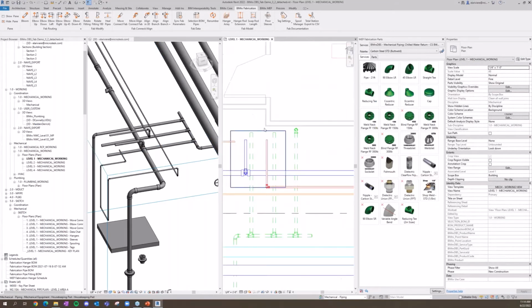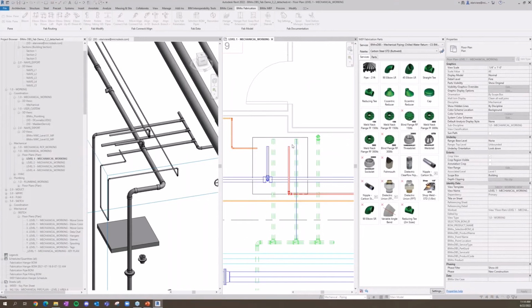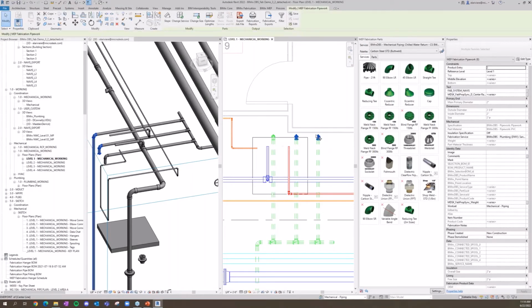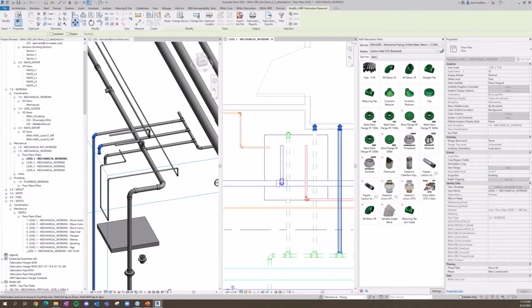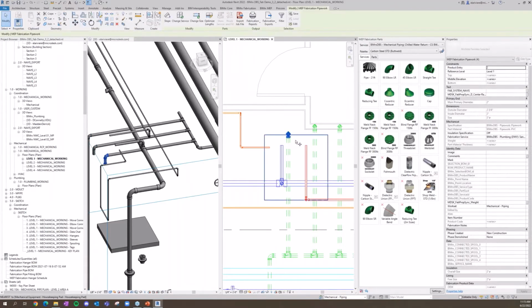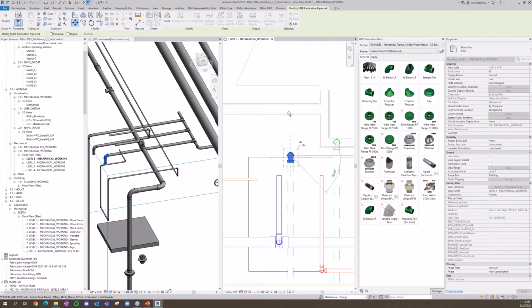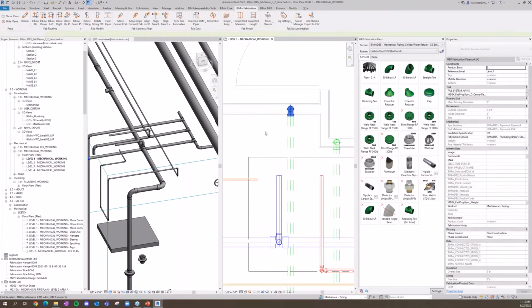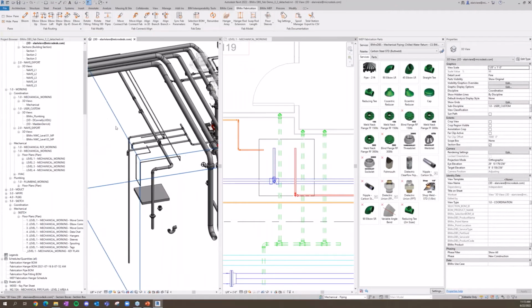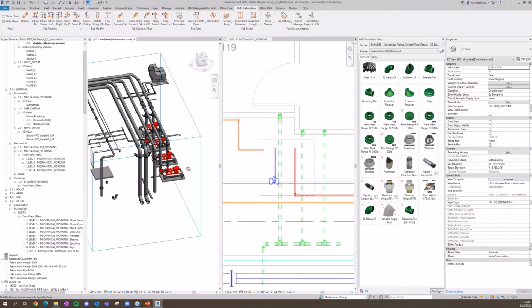And maybe you do want to use those elbow commands in 2 dimensions. Maybe you're looking to drop some elbows down over here so you can grab a few of those elements and move them into the wall, right? Like I said, I'm a big fan of using the 2D view as a reference and doing that heavy lift and modeling, coordination against other trades. I'll do that in the 3D view instead.